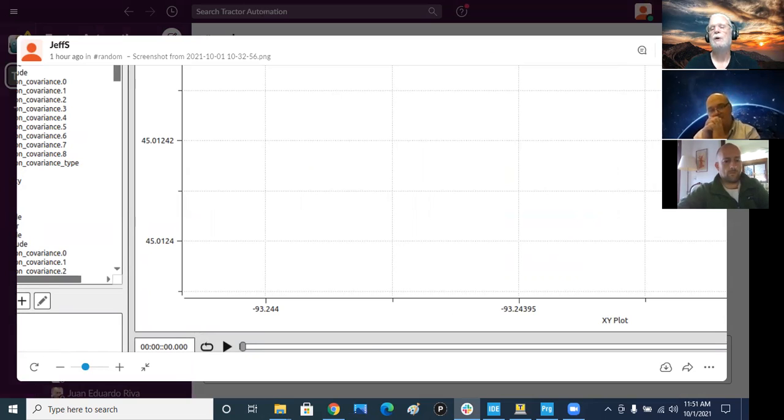So on the AI stuff, what I'll do is write a new node that subscribes to these and creates a topic called recovered angle, and then have it publish that. Then I can start up the record, and what it'll do is take his original file and add in the new topic. So when I'm done, I've got a new bag file with that stuff in. I can pull that up in PlotJuggler and then compare everything together at the same time.